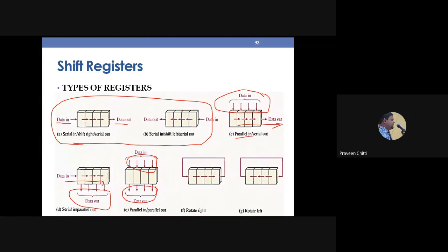And in this shift register, whatever bit you are shifting out, you are giving back. Such shift registers we can call cyclic shift registers. From this end you can put, or if it is going out from this end, you can enter it from the other end. So this type of shift register is called a cyclic shift register, where the rotate operation takes place. Whatever is stored in it will be rotated and will come back again from the other end. In the earlier cases, whatever you enter from one end goes out the other end and vanishes; it will not come back. But in this case, whatever you are shifting out comes back again from the other end. That's why it is called the rotate operation.